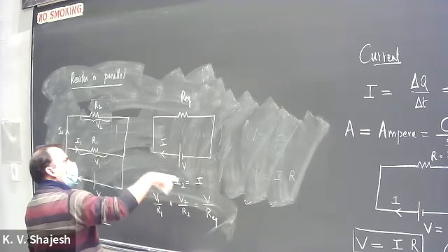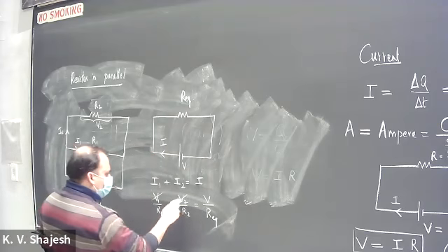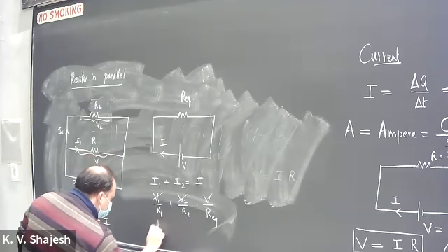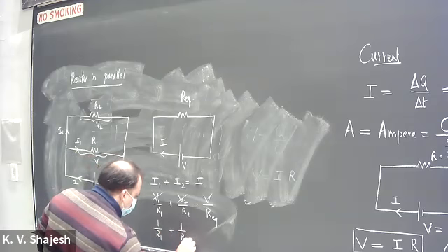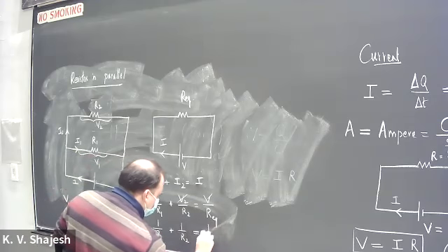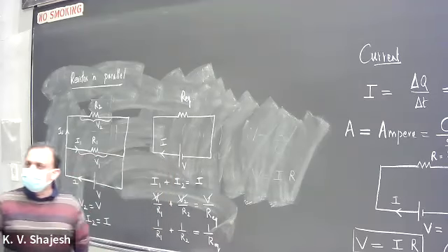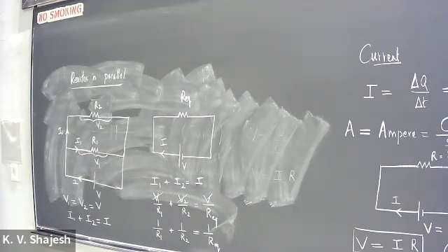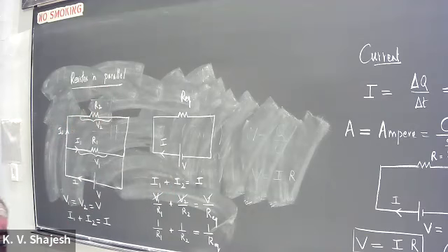Like whenever it comes to the total, that's the effective resistance we have. But this time the voltages are the same. So voltages cancel and we see that the inverses of the resistances add up to give you the inverse of the equivalent resistance. And if you remember, that's what happened in the case of capacitors in series. So capacitors in series and resistors in parallel are mathematically equivalent.